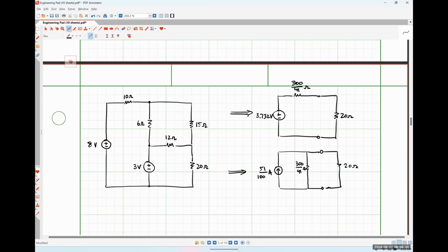So based on what we have here and what we learned in class on Wednesday, it should be fairly obvious that since the Thevenin equivalent circuit is electrically equivalent to the thing on the left, and the Norton equivalent circuit is electrically equivalent to the thing on the left, then the Thevenin equivalent circuit must be electrically equivalent to the Norton equivalent circuit. They are just source transformations of each other. So that means we can verify our answers inherently, right?